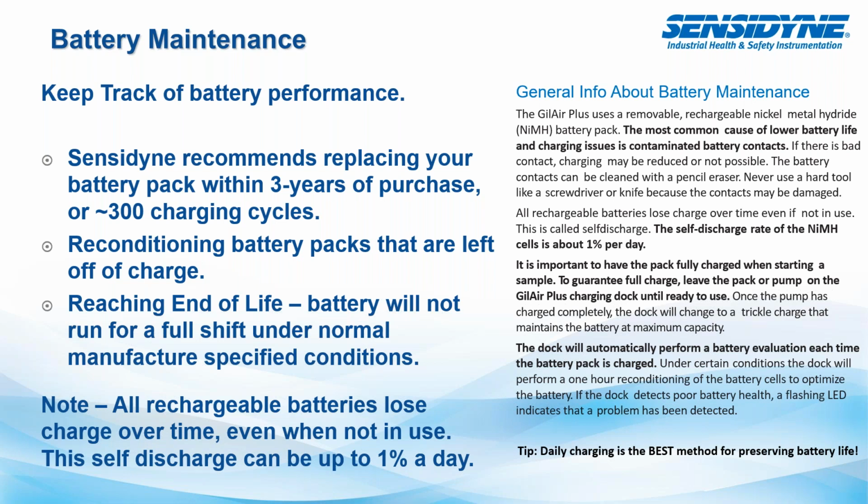So if you have it sitting around for 3 weeks, you've literally lost at least 20% of your battery capacity in that time period. If it goes 3 months, your battery will have almost been completely drained. So it's important to recognize that and make sure that you're getting the right power in it. Also, if your battery has sat for more than 3 months and it has fully discharged, you may have to recondition that battery to get it back into a